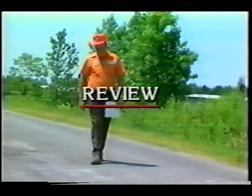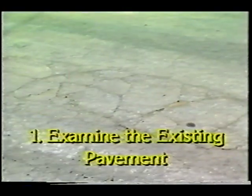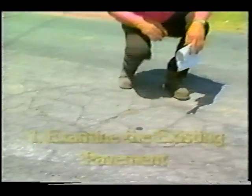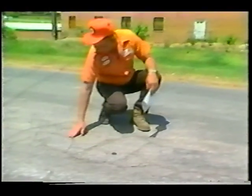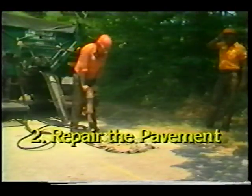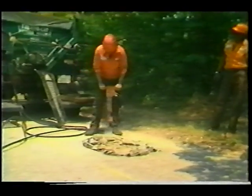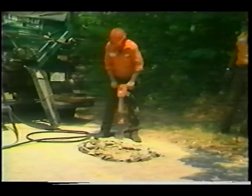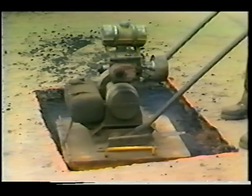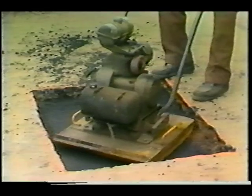Let's briefly review the 7-step procedure for installing an asphalt chip seal. Step 1, examine the existing pavement. Examine the pavement for surface distresses and drainage problems. Step 2, repair the pavement. Complete pavement and drainage repairs prior to the installation of a chip seal. If these distresses are not repaired prior to the seal placement, they may reappear soon afterward.